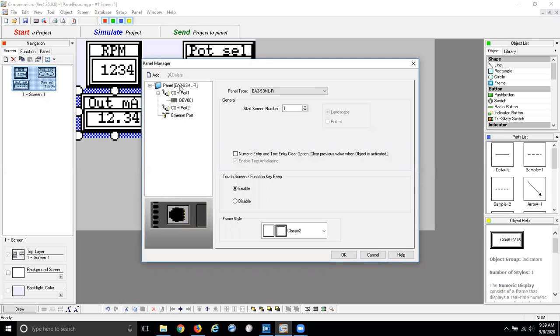So what you have to do is you have to tell the communication path between the panel and the device or the PLC. So you have to configure that. This would be the little white cable that we use to locally program. So it's going to come out of the panel and go into the PLC. And so you basically have to tell it how it's communicating.